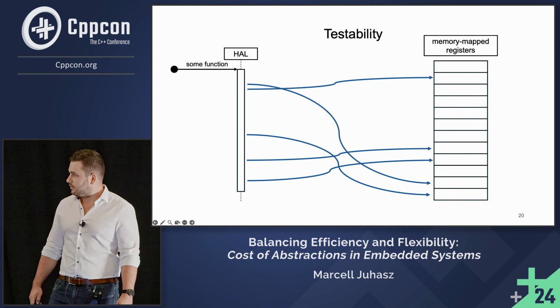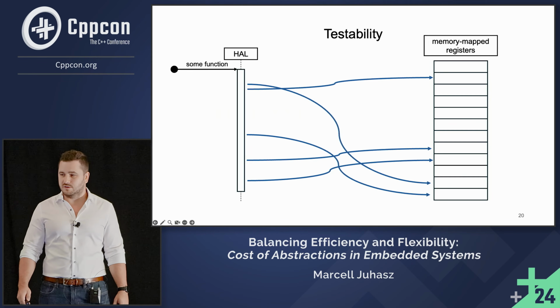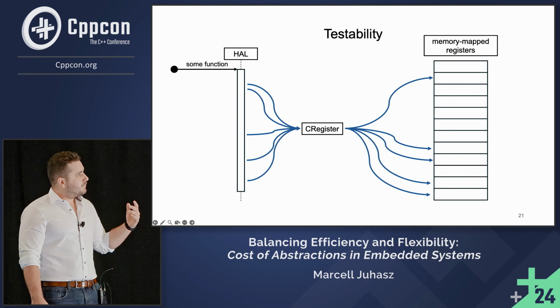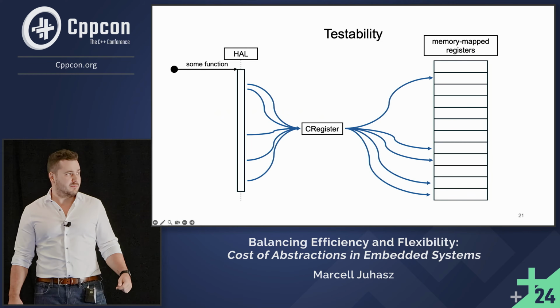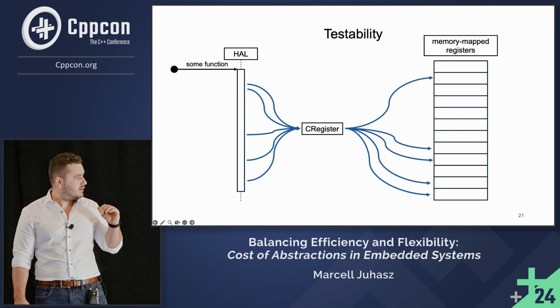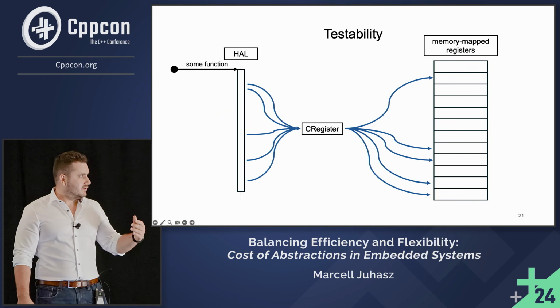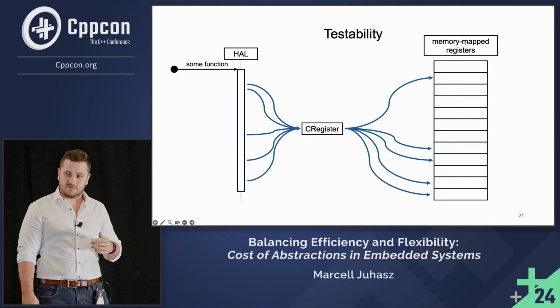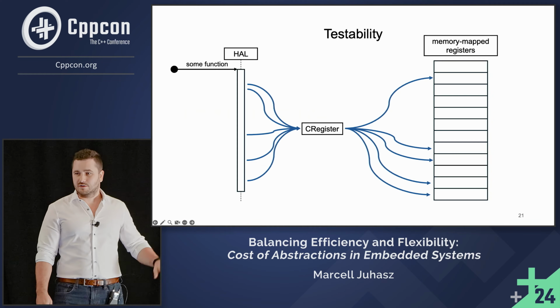You probably know that desktop applications do not really like it when you access memory that is not yours. But when the register operations are encapsulated this way, it makes it possible to simply replace the implementation of the C register class, because every access to fixed memory locations is handled in a centralized way by the C register class.